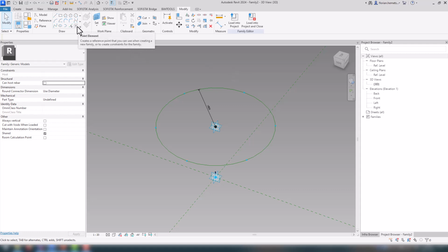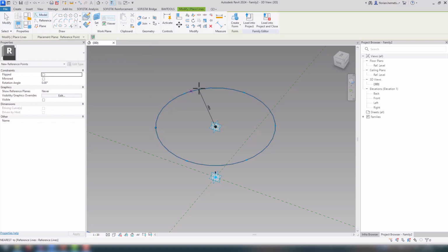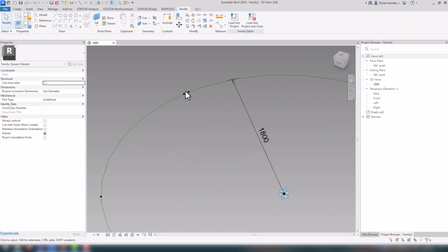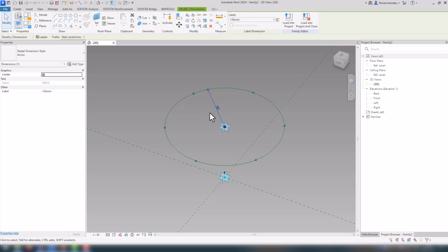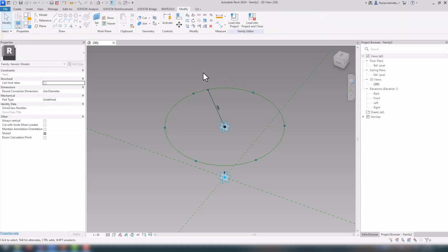We will do this parametrically with point elements, and we will select the, I actually didn't hit this one. I will come back to this one later, but we will select our 6 points over here. And this one I will get rid of. Why did I do this? Because if I now come into here and assign a proper length to this one, we could now change the width. I will show this once we created our reference geometry.